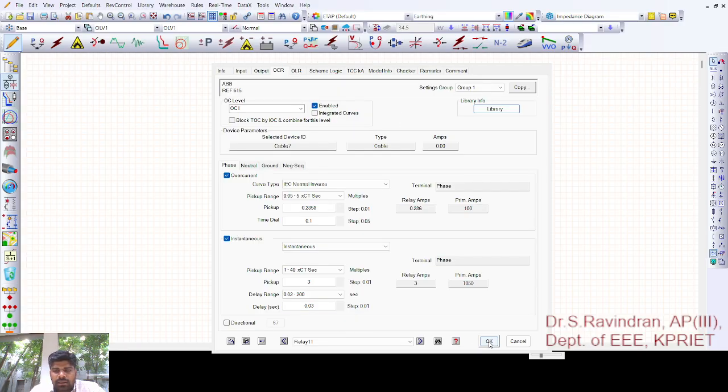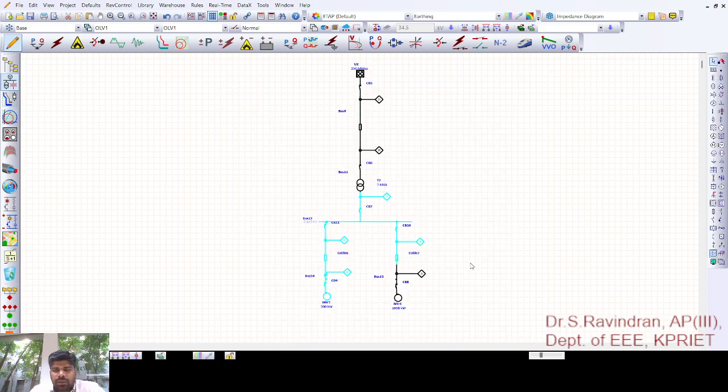It is taken. I am setting it. Now if a fault happens over this point, this relay will operate in this manner, so I should set this relay's time less than that, and this relay's time more than that. Likewise, I need to set these parallel operating relays based on their current value, the timing, everything. So this is a system.